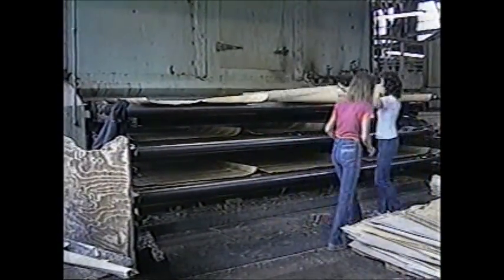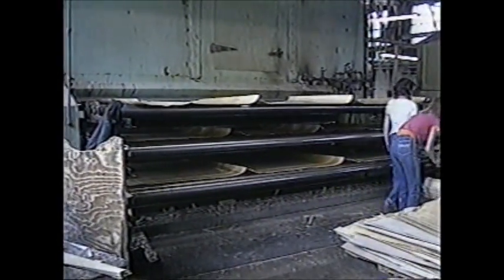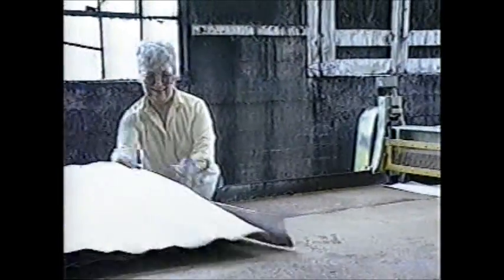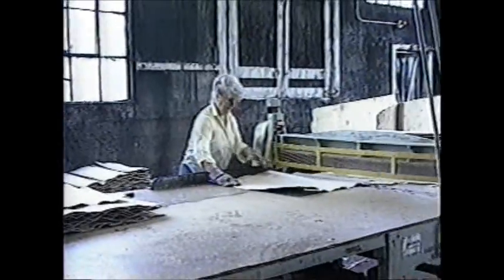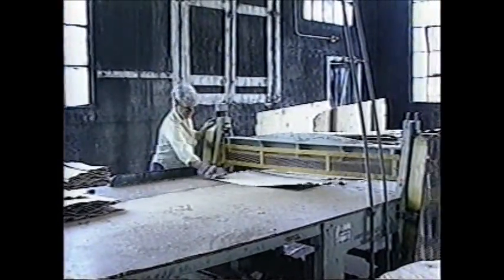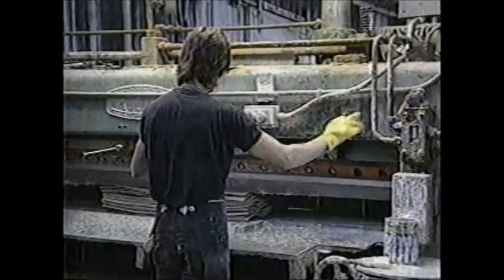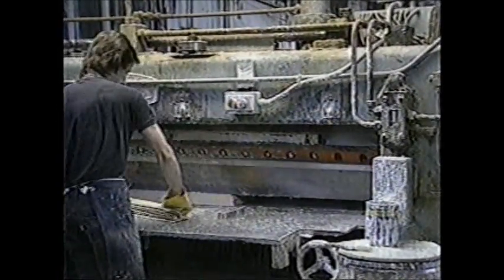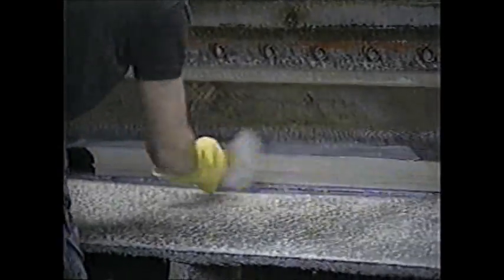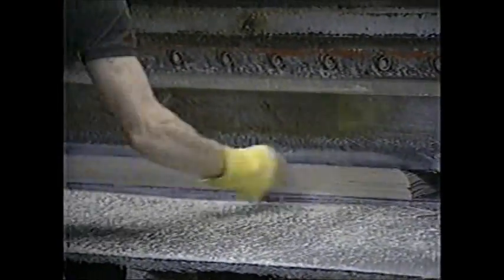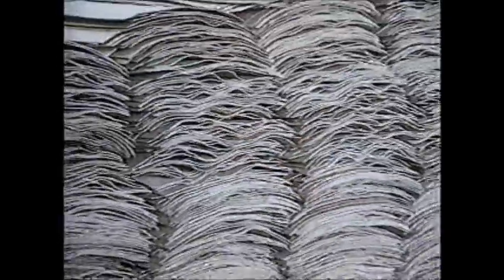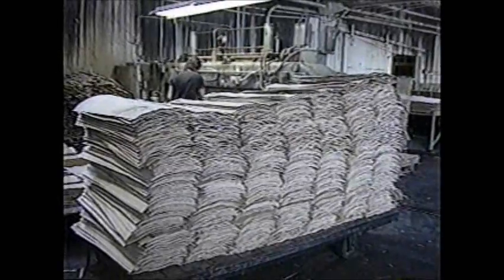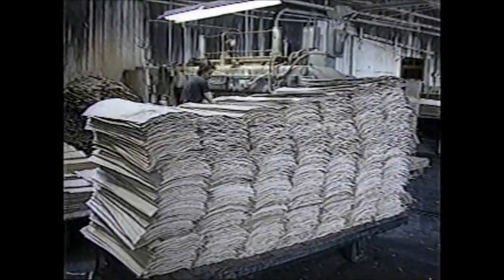The sheets of hardwood veneer are carefully dried to a moisture content of 5 to 7%. Smaller, high-quality pieces of veneer are hand-clipped from sheets containing defects after drying. After drying, narrow pieces are carefully trimmed to standard sizes and coated with the urea formaldehyde resin glue. The adhesive is heat-activated and cured. These narrow pieces will be edge-glued to form larger panels.